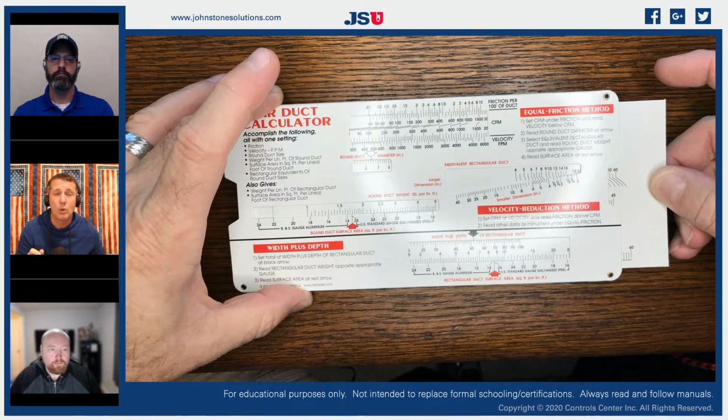And when we look at our coils, we have wet and dry calculations for those coils. And what you'll find, and Jesse and I just encountered a bunch of them here just last month, we were looking at the wet bulb wet calculations on an A coil and found that some of the coils on our high efficiency equipment had like 0.37 inches of static across that coil, a 3-ton coil. So that doesn't leave you much room for failure, right?